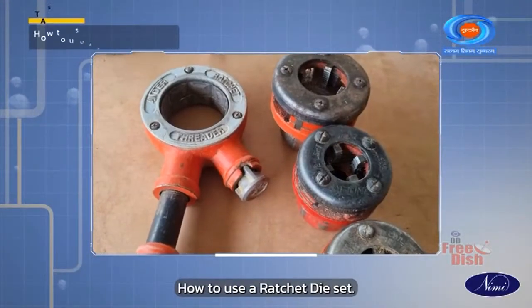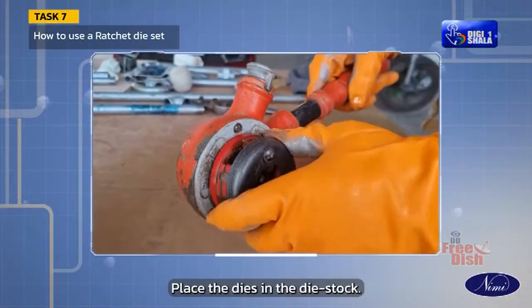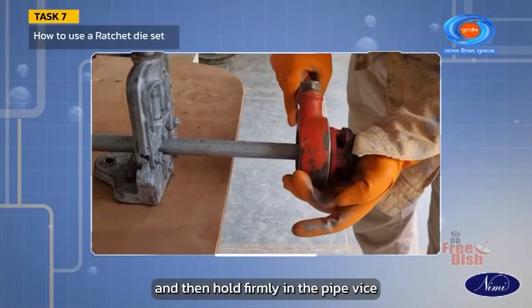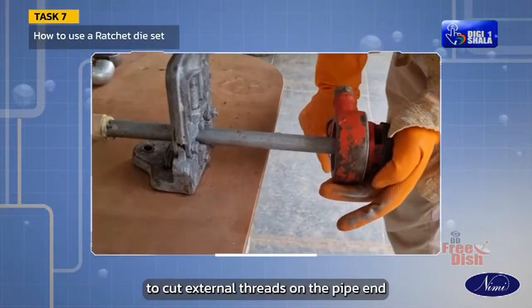How to use a ratchet die set. Select the die according to the size of the pipe. Place the dies in the die stock. Place the die set on the pipe end and hold firmly in the pipe vise. Rotate in clockwise direction to cut external threads on the pipe end.